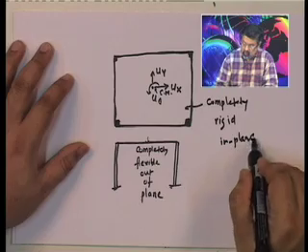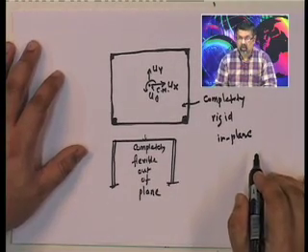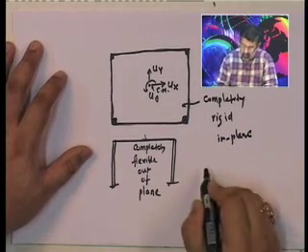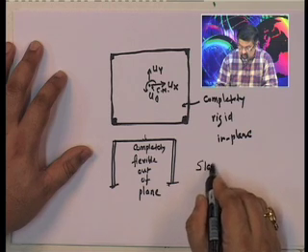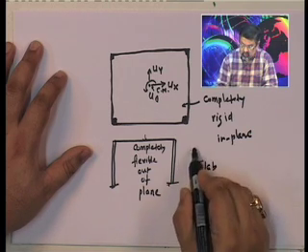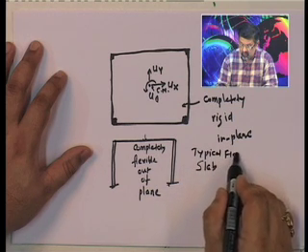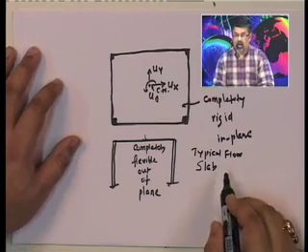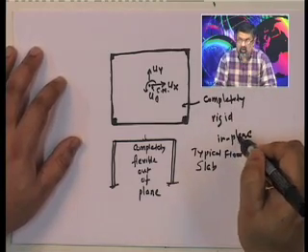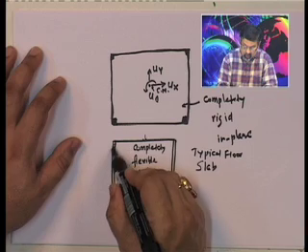In plane it is completely rigid, and this is typically what you assume, the typical floor slab assumption, where it is considered to be completely rigid in plane and completely flexible out of plane.